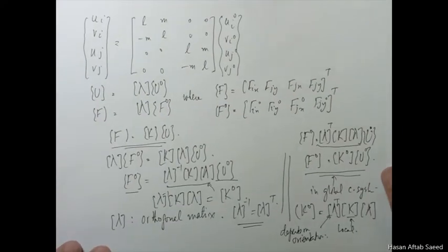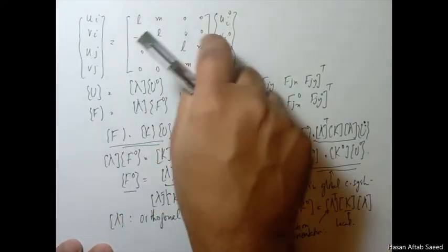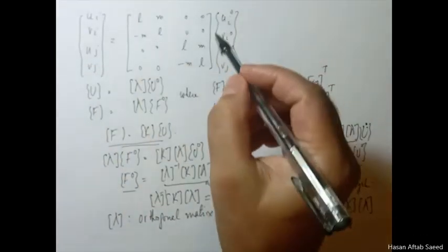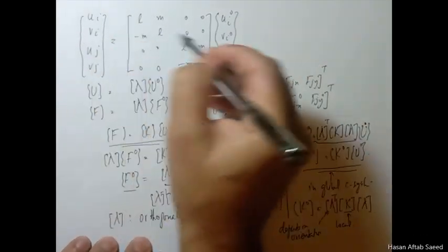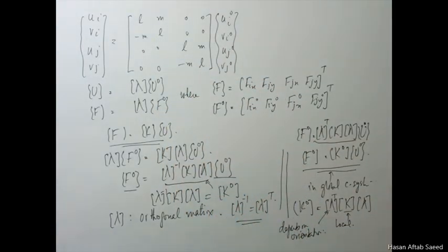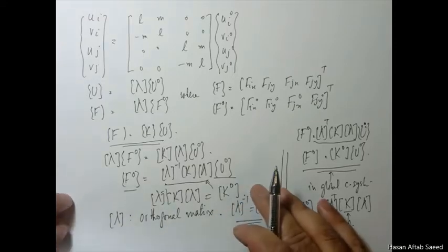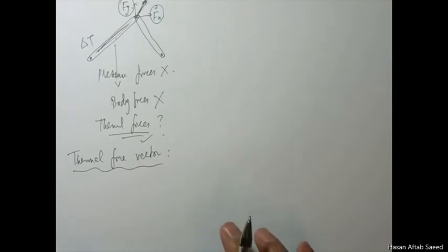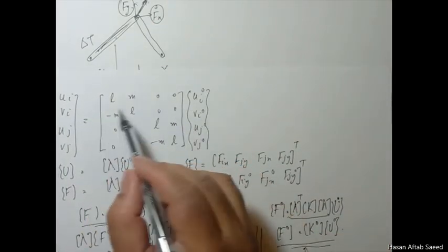For this we have to again come back to our original transformation equation. This is the way you transform from global to local using the lambda matrix. Now I can write this again in terms of forces, and we have already mentioned that this transformation is not for displacements alone, this is also for forces.